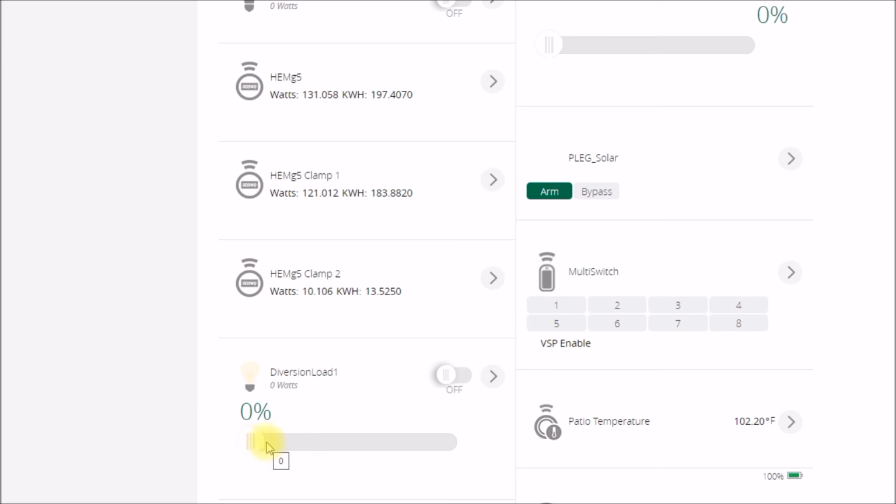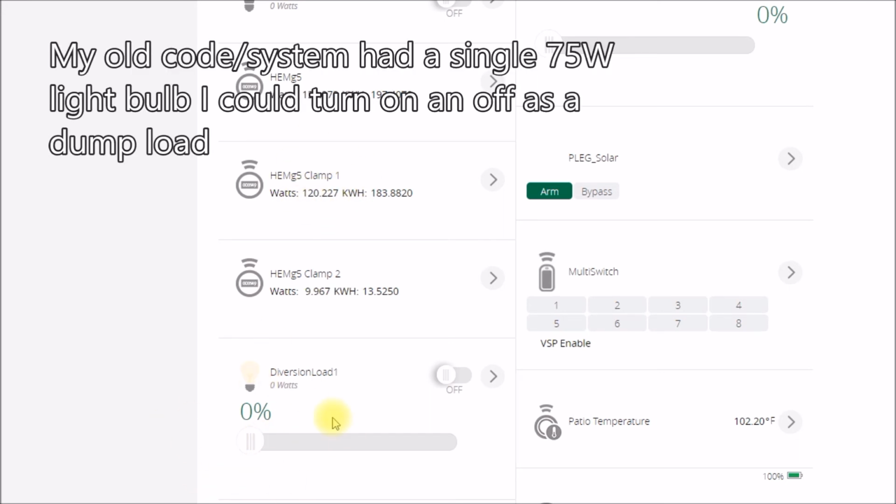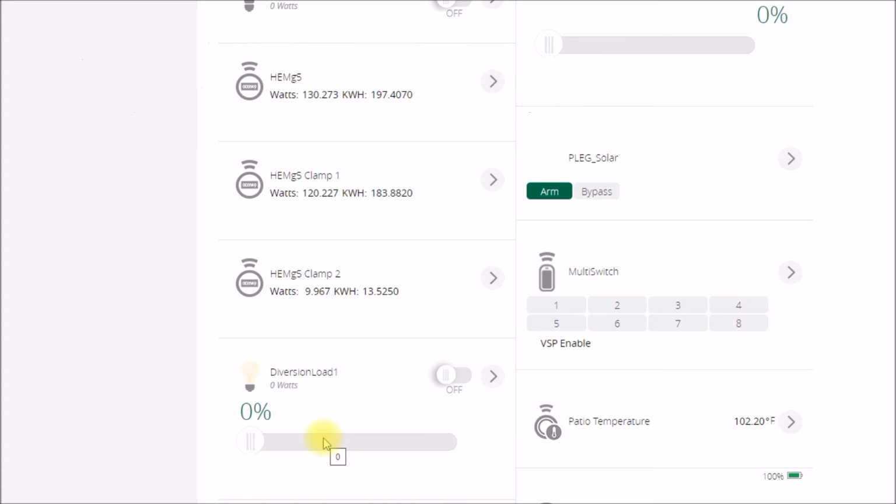So it does the 5% from the initial trigger, and then it does maybe 2 more increments with the checking this power below 25 watts. So it's not really very sophisticated, but it does actually do the job, and it turns on when it's supposed to, and it turns off when it's supposed to, and it keeps the power in the range of 25 to 50 watts. And it'll sit here and cycle on and off during the day.